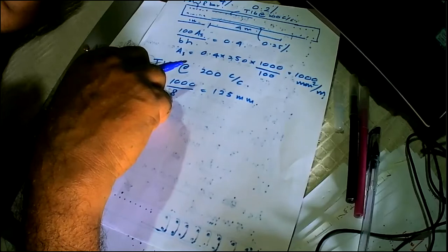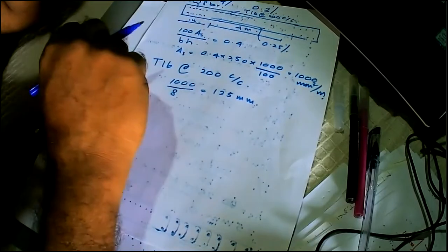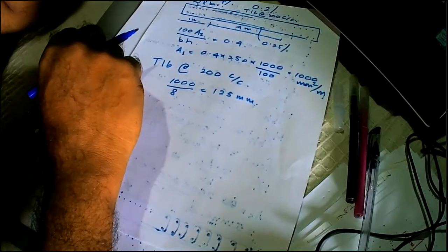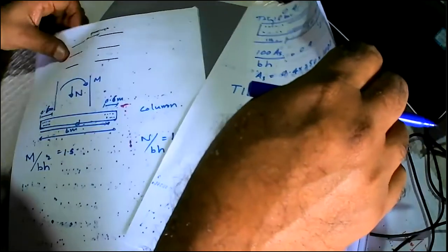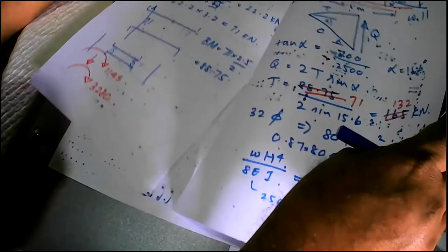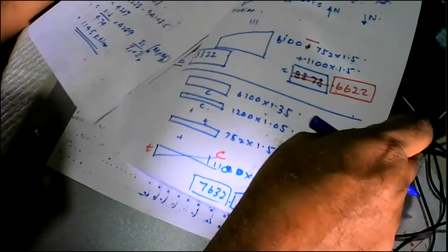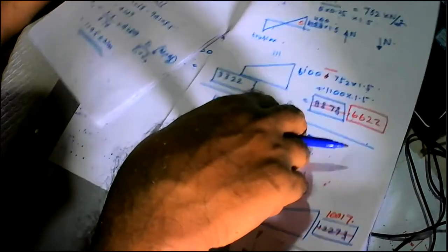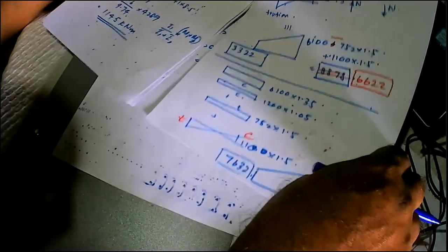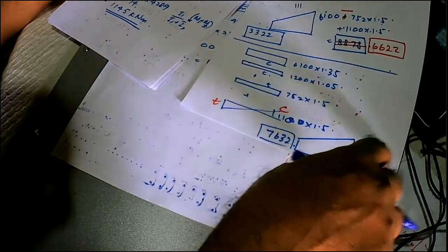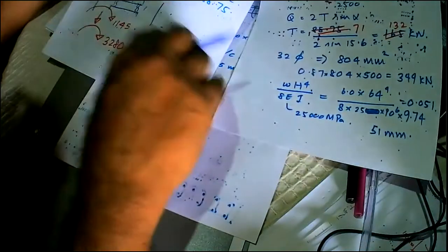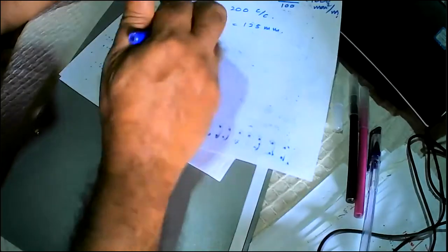Anything else? So this is one way of finding the reinforcement in the concrete wall. And then there's another way of finding the reinforcement in the concrete wall, because in our calculations last time, if you look at the calculations, we found the stress distribution. We actually found the stresses in the wall, right? And we found something like 10,000 kilonewtons per meter squared. Is that right? So let's say we have a wall,